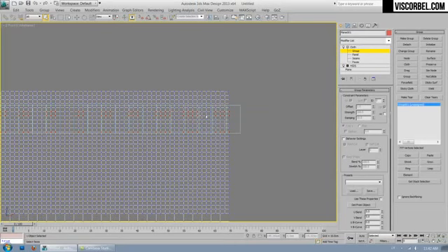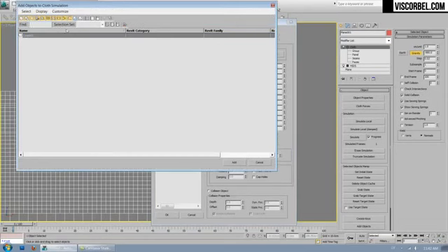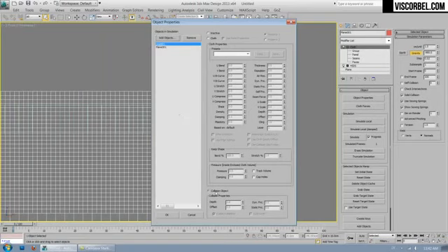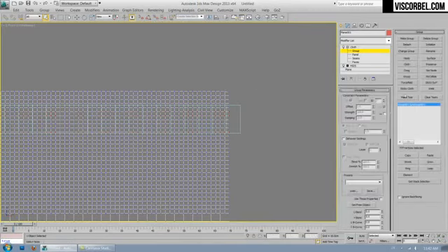And now we want to attach this group to this box. Okay, so first let's go to Object Properties and make sure the box is added to our simulation and set to Collision Object. And now we can go back to our group and click on it right here and then choose the Surface mode. And now you have to click on the box to attach it. Okay, good.